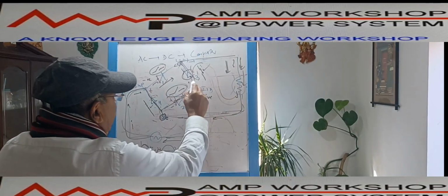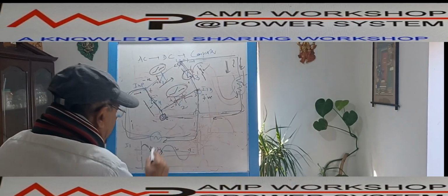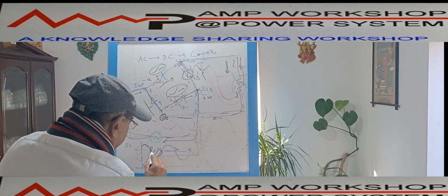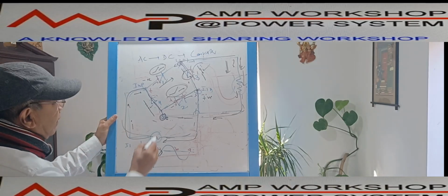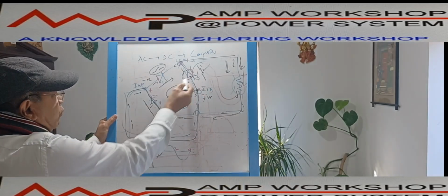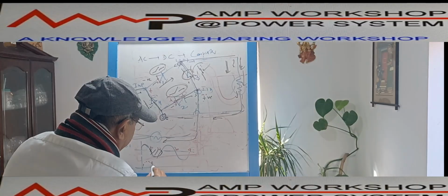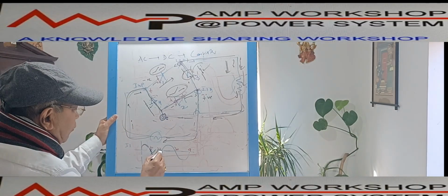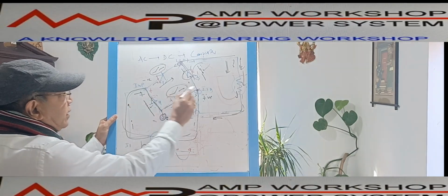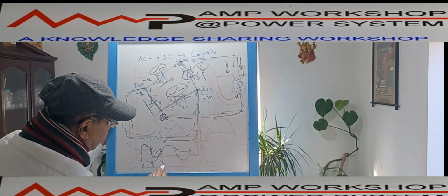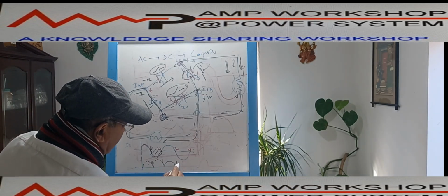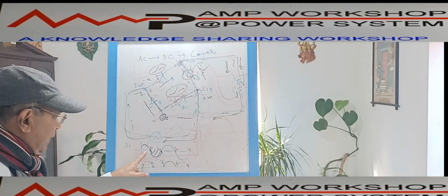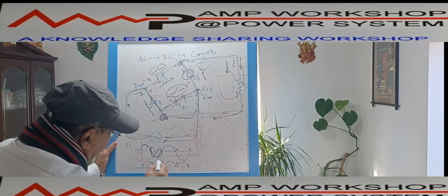That means if you draw the load current, in the first half cycle the current is in one way, and it is replicated over here for the first 10 millisecond. In the second 10 millisecond, diode 3 and 4 are conducting, but the load current is in the same direction. So it is a replica of the same direction. After 20 milliseconds, again it is positive and negative, so it will be replicated. Then in the next cycle, it will go this way. That means by this arrangement, what is happening? The alternating negative part is also converted to positive part.